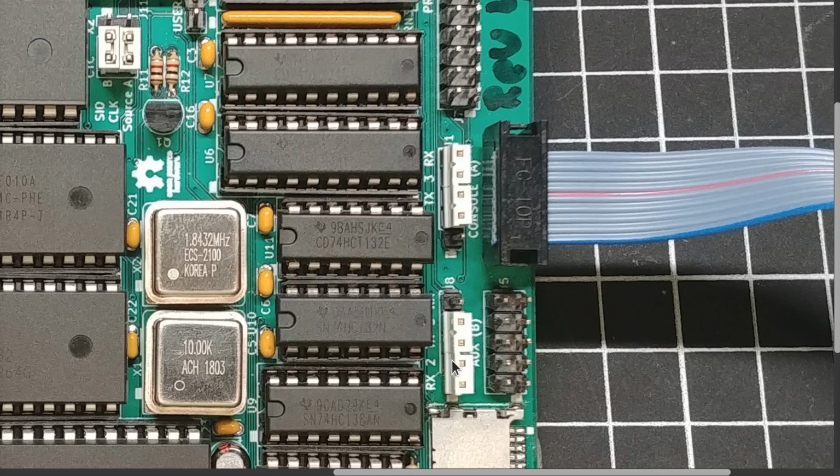That way you're always able to just reach in here and fix it when you've got the wrong kind of cable or adapter, or the gender's wrong, or the bits are reversed, the null modem, and all that goes away. Just hook up pins 2 and 3. Pick which way you want them to go based on these jumpers.